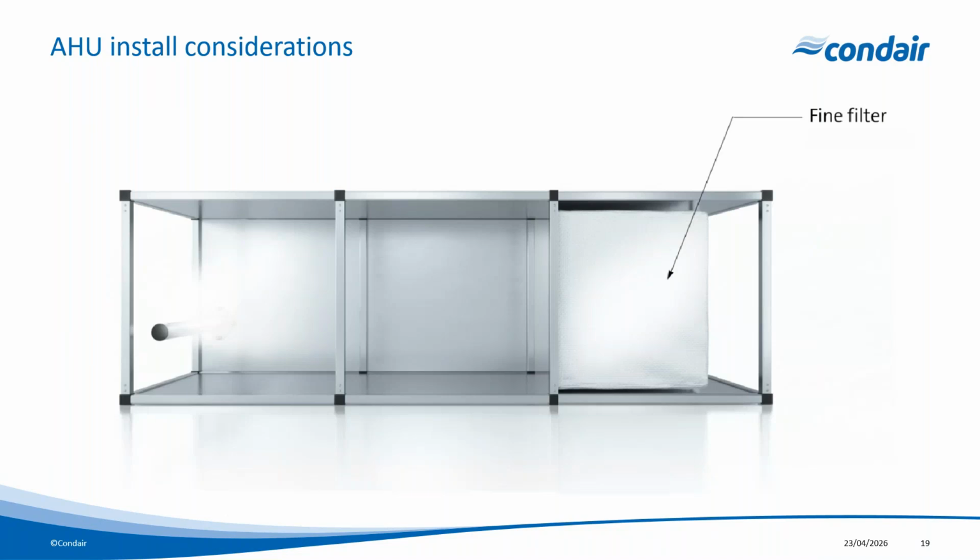And if you are sensing in the supply air, then the sensor location or high limit stat must be 5 times the absorption distance from the steam lance. So again, these are all part of the system that are going to have a critical effect on the performance and ensure that the system isn't going to wet out.